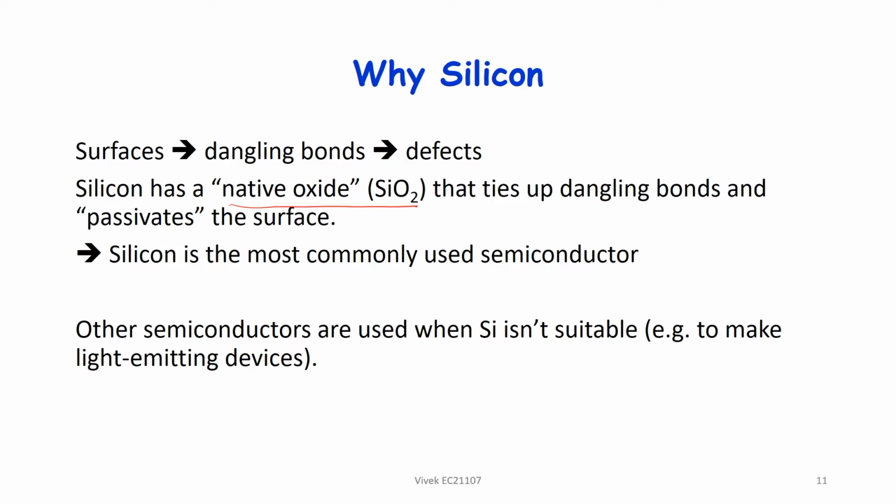If you look at any semiconductor, inside the bulk everything is okay because all the atoms are bonded to neighbors, but at the surface not all atoms are bonded, so there will be dangling bonds. Now these dangling bonds are actually defects, right, because these bonds are free, so they will try to attach to some other foreign atom, could be impurity, anything, right? So they are actually defects.